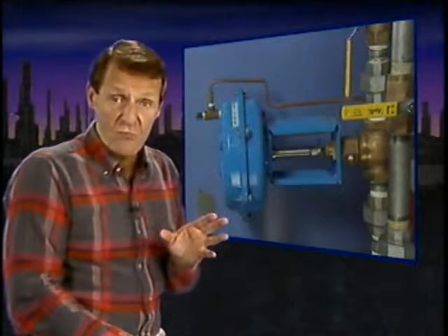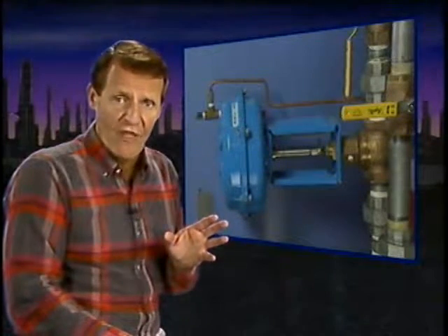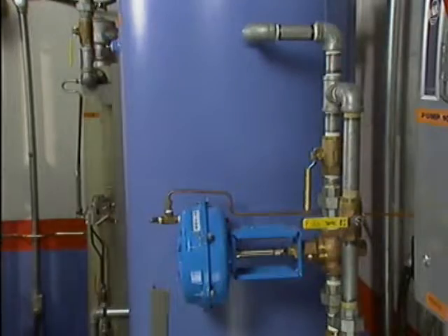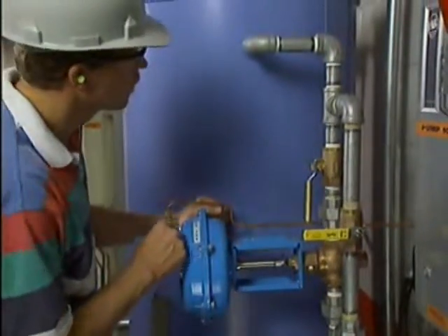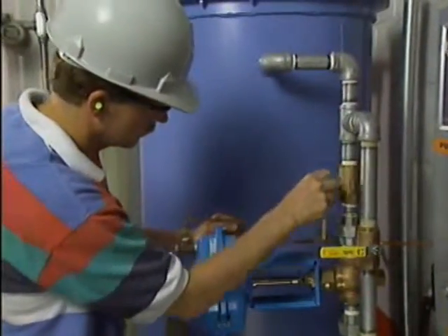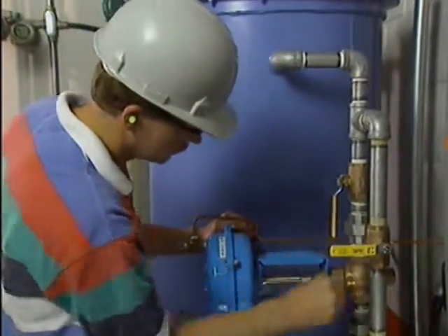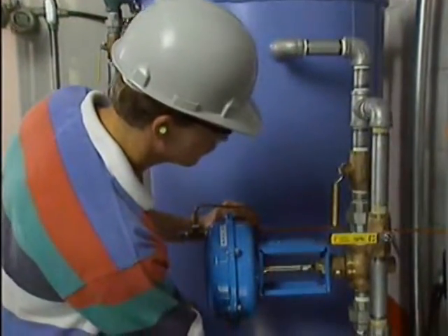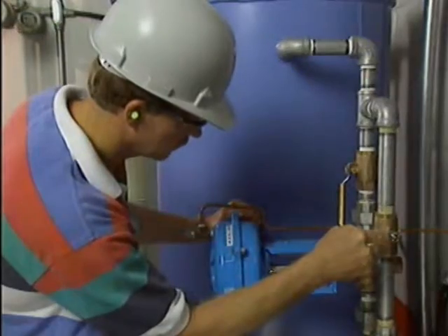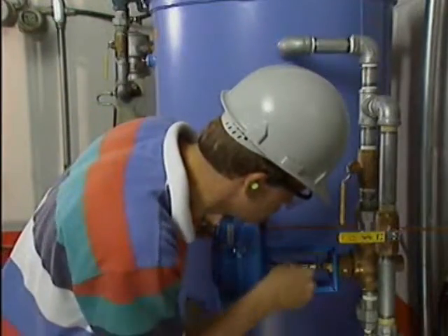To find the cause of the problem, the outside operator inspects the recirculation line control valve for obvious signs of damage or problem. When he inspects the valve, he can find no signs of obvious damage to the valve or the valve operator. Also, the local valve position indicator shows that the valve is shut, so the outside operator believes that the valve must be leaking by its seat.